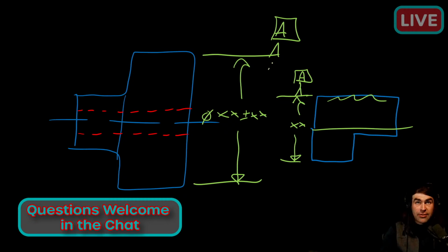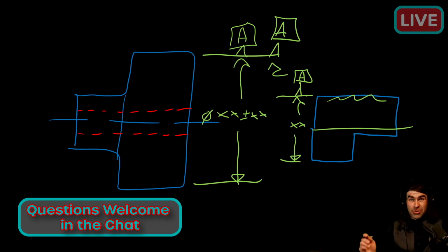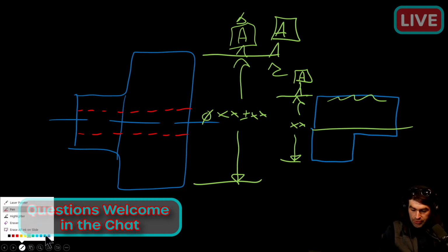Normally, you could just scratch this up to, okay, whatever, they just meant to put it here. But you're going to run into problems with that when you start interpreting what the designer meant to do. It's possible they were trying to use datum targets. There is a technique with datum targets where you can have line contact on the outside of a cylinder. You wouldn't mark it like this, but there is a situation where you could. I drew that one too big, but I'll draw another one over here.